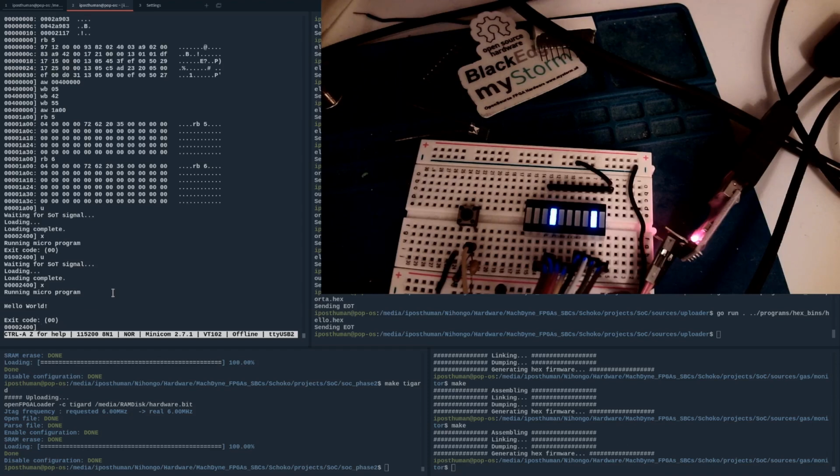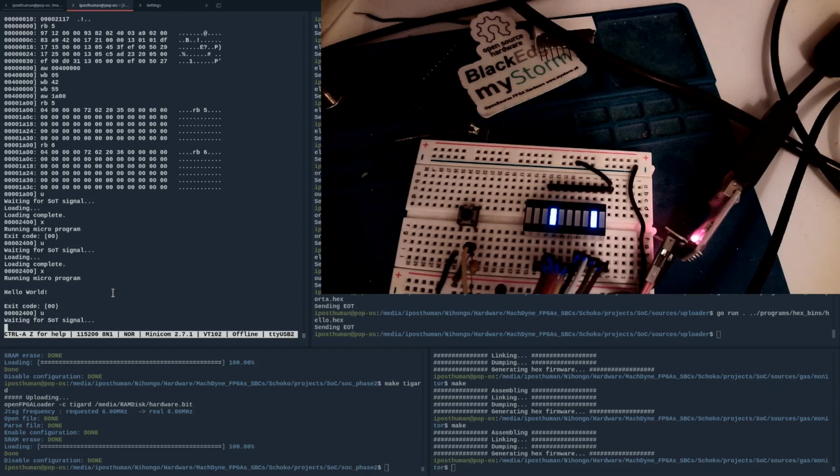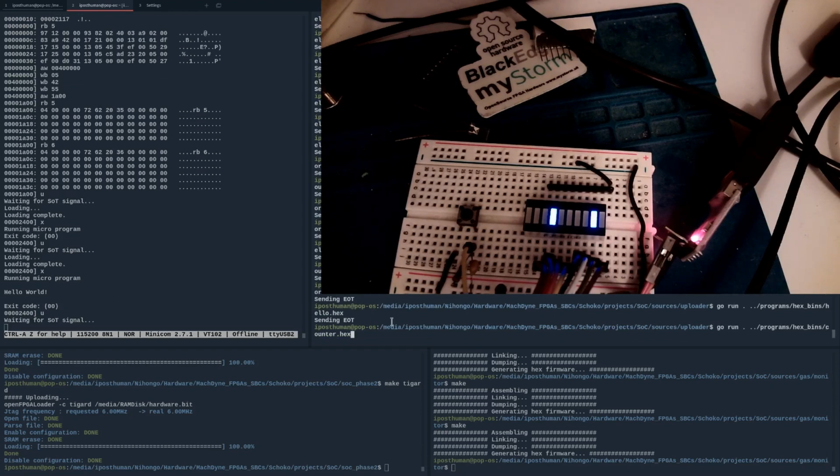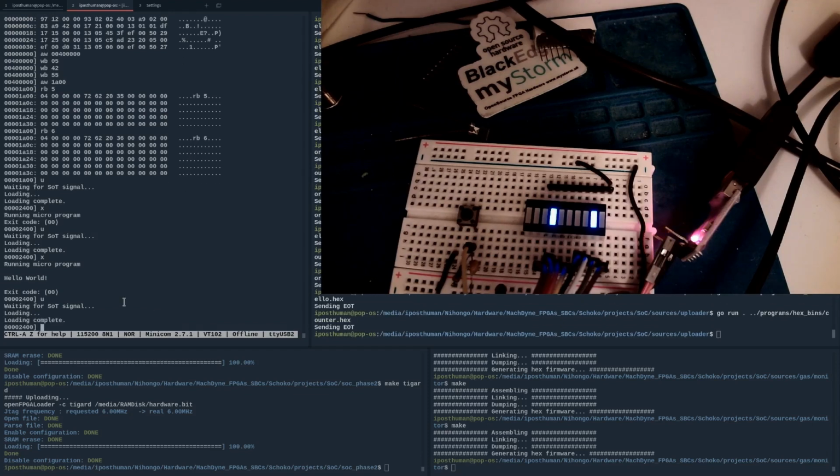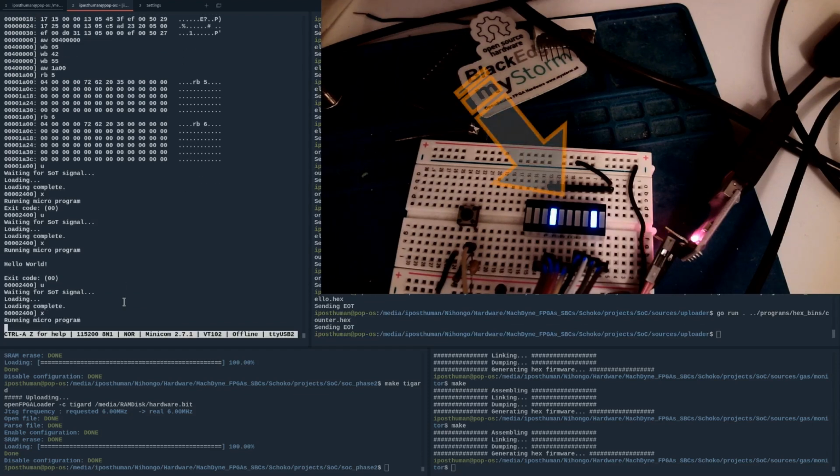So let's upload a program that doesn't exit when it's finished. And this is what it all comes down to, is using that Control C. So I'll hit the U command and I'll update the counter. And now I'll hit the execute to run the program. And you'll notice that the LEDs down below are now counting up to the FFF, or just F. And then they'll recycle around.